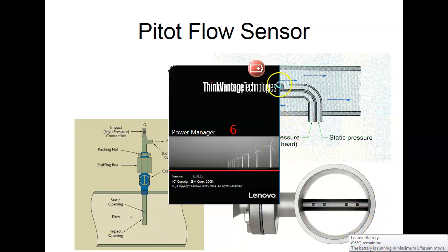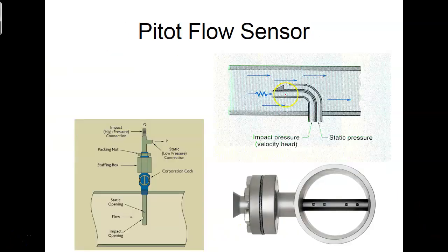Yeah. Sorry. How did I do that? So this would be the one that's measuring what? The static pressure. And this would be the one that's measuring the actual ram pressure. And then they compare them against each other. Because in an airplane, the higher you go, the less flow you get, right? You understand that? Because it's thinner. That's why they would compare it against a static pressure, and they would always get the right airspeed. So they wouldn't if they were using that type of airspeed.